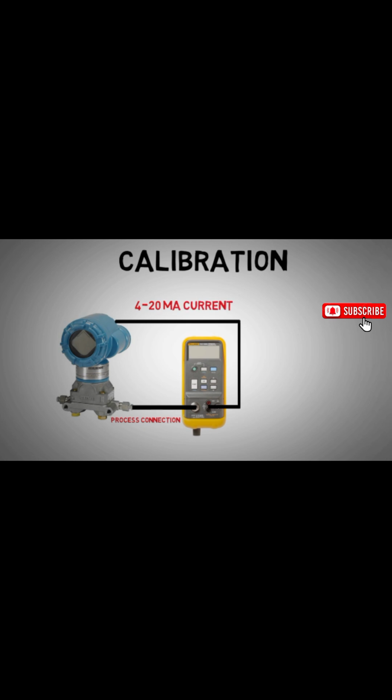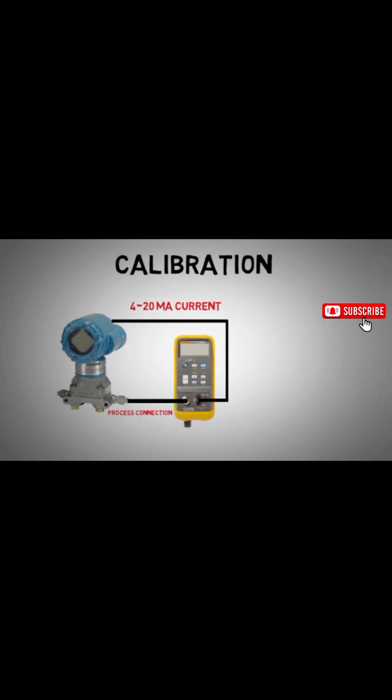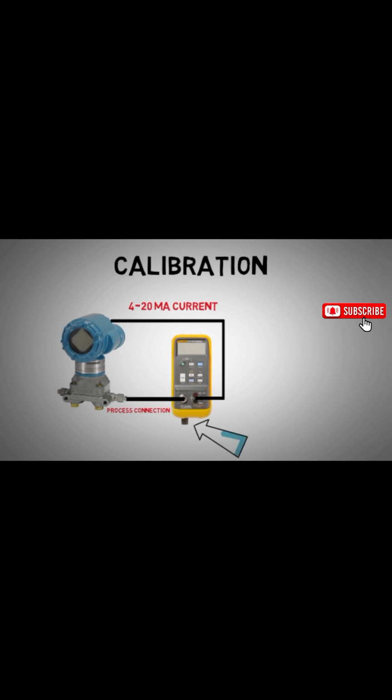Also, you will need to connect a calibrator to simulate the 4 to 20 milliamp signal. Now, the transmitter will give you two different outputs via the control system, and it will convert our reading into the process value that applies for the various test pressures.